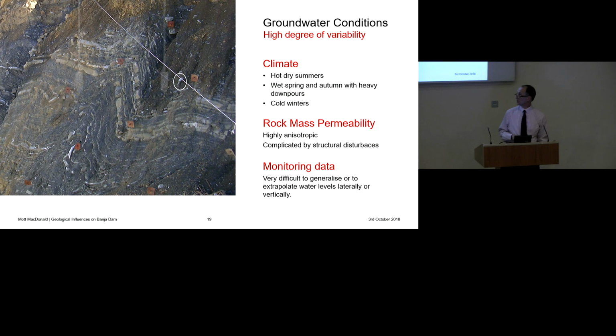So if you imagine 2 piezometers drilled and installed to the same depth, but maybe 5 meters apart, the one on the right will undoubtedly pick up some response from the groundwater, and you'll get a reading. And even if the flow isn't great, you might well get quite a reasonable pressure in that piezometer. But you'll get absolutely nothing on the one on the left, and it's only 5 meters apart. So it's very difficult to generalise and say what is the groundwater table, because it's so heterogeneous.